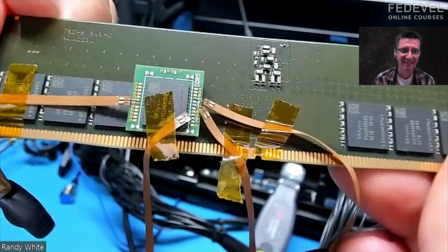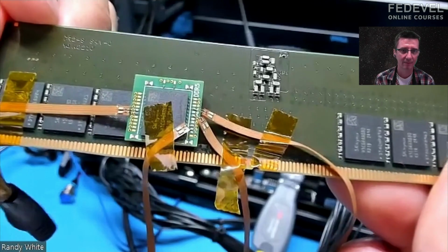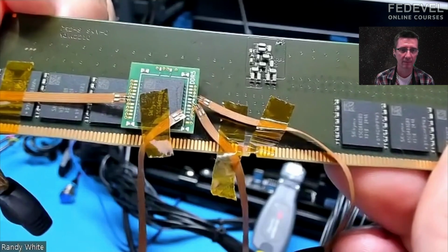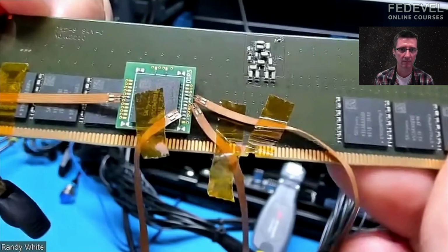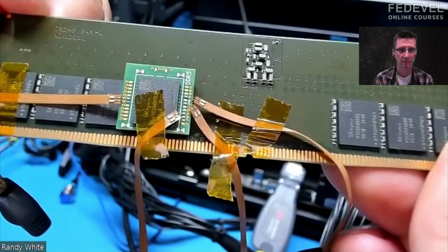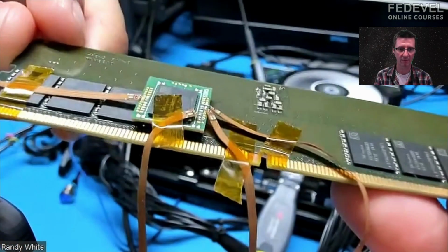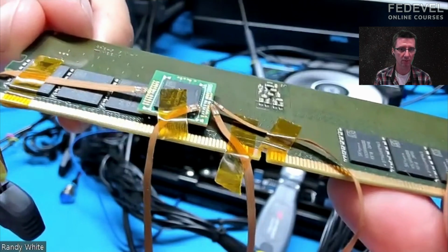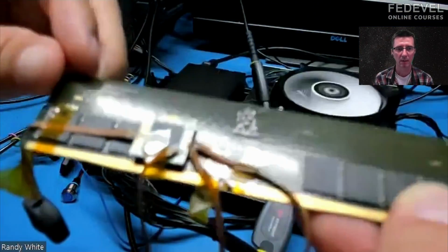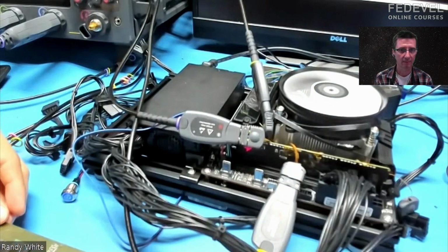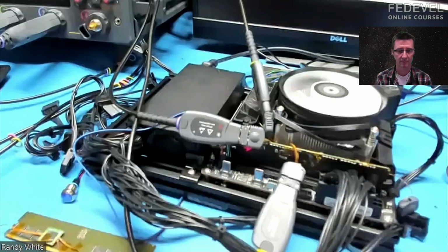So here I want to access clock, chip select, and CA, just one of the CA lines, there are 14 CA lines. I just want one CA. Of course data, DQ, and then DQS. We will talk about this a little bit later, but this is very important. Everyone who would like to measure memories, remember what kind of signals we need.